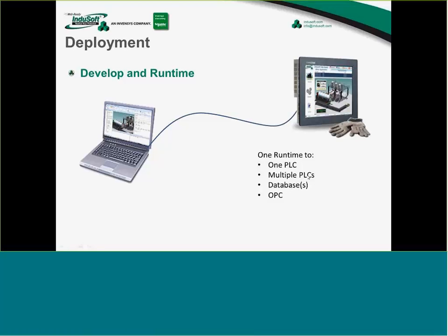And by multiple drivers, I don't mean multiple PLCs, because you can do that, but each driver might have many PLCs on that. So even though your license might support, let's say, 3 drivers, that's not 3 PLCs, that's 3 driver networks, each supporting however many that PLC protocol supports.